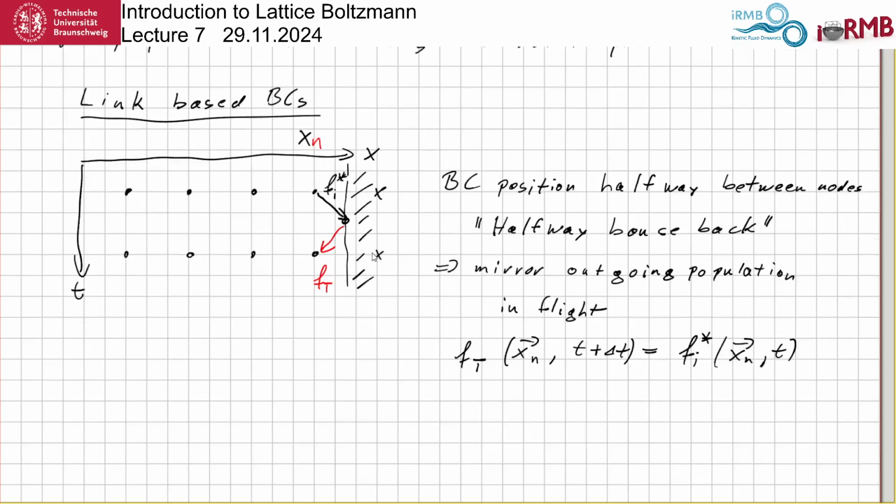So what this does is it produces a velocity zero boundary condition, which we call a no-slip. So velocity is equal to 0 in both directions: no penetration and sticking. So the velocity at the boundary is 0.